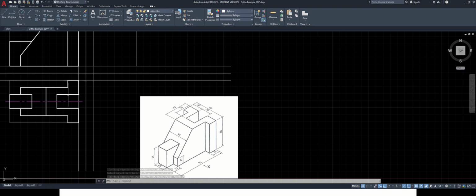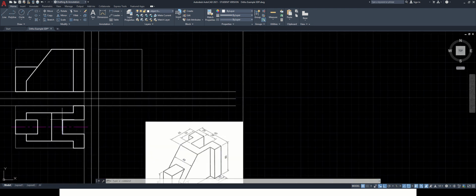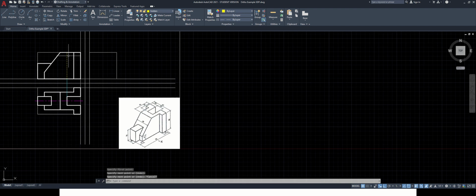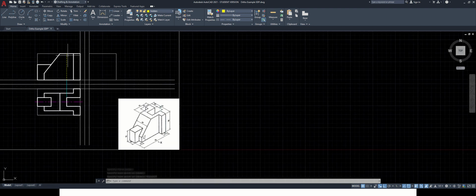So this is how we have completed our top view. Now as we have said, there is one thing remaining. These projections have to be taken over here in order to draw this hidden line. So I will switch on the layer of projection, go to line command. These projections we can take. Again I will switch on hidden layer, go to line command. Here to here, throughout there is a slot, right? So it will be entire hidden line.